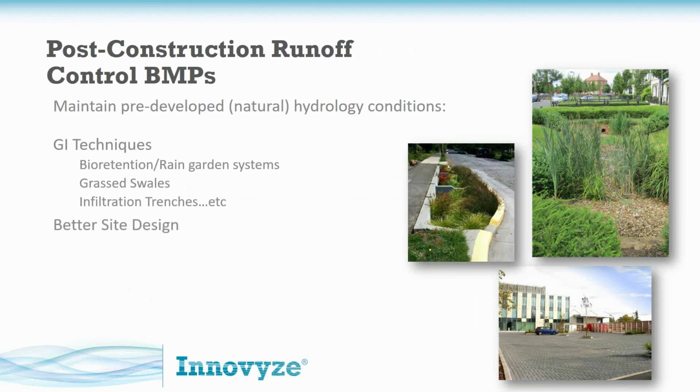But what I want to call out is that larger scale best management practices, green infrastructure, it's not, again, just a couple ponds, right? It's a larger practice of distributed treatment across a site, okay? That might be back in the 70s, the bread and butter was to put just one giant detention pond at the end of some sort of drainage catchment. Well, that's really not an effective way to treat, as we'll talk about, and maybe not the best use of space. So distributed smaller facilities all across a development.